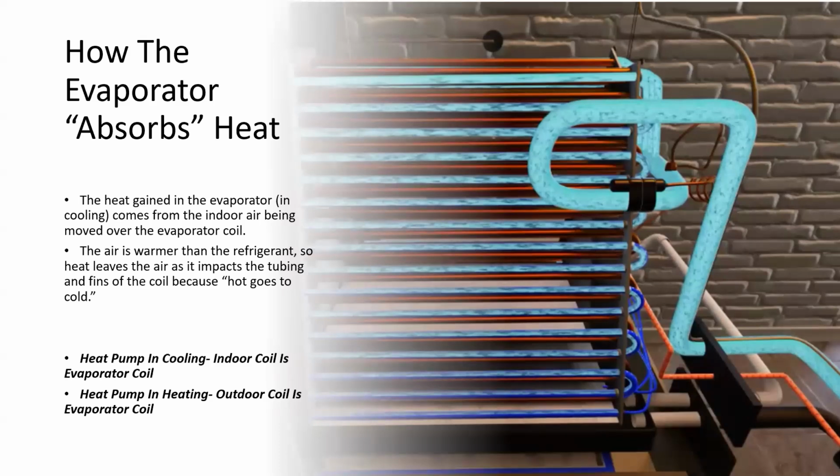The refrigerant in the evaporator is at saturation, it's at boiling. The coil temperature doesn't directly change as heat is added to the refrigerant, but it begins to increase indirectly. So as the total heat energy in the evaporator increases, so does the coil pressure, and vice versa.